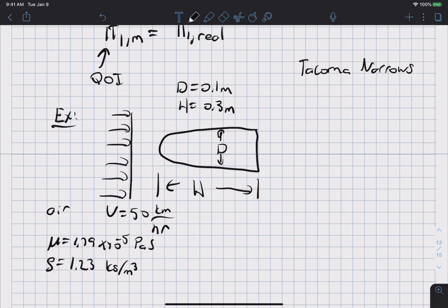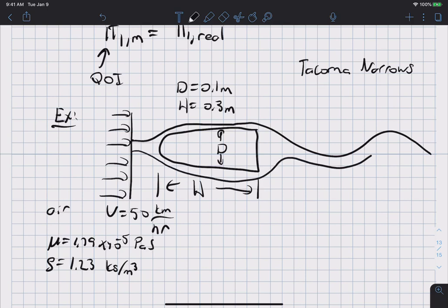And so fluid mechanically, what happens under certain flow regimes is that the streamlines just don't go over and around the object like you would imagine, is that the flow actually oscillates back and forth. And so the streamlines will look something like this. And it'll go up, then the streamline will go something like this. Okay, and in these little troughs here, there are pairs of counter-rotating vortexes.